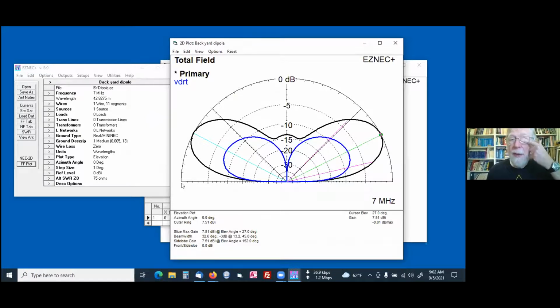And even at a quarter wavelength, your dipole may be a lot better if you're, like I've got a friend in San Francisco that I have a weekly sked with. It's about the only operating I really do except field day. And it's about 600 miles to San Francisco, which is about 1,000 kilometers. And the angle for talking to him is around 30 degrees. And so the dipole, even at a quarter wavelength, beats the pants off a vertical for that path. And at a half wavelength, it's a real killer.